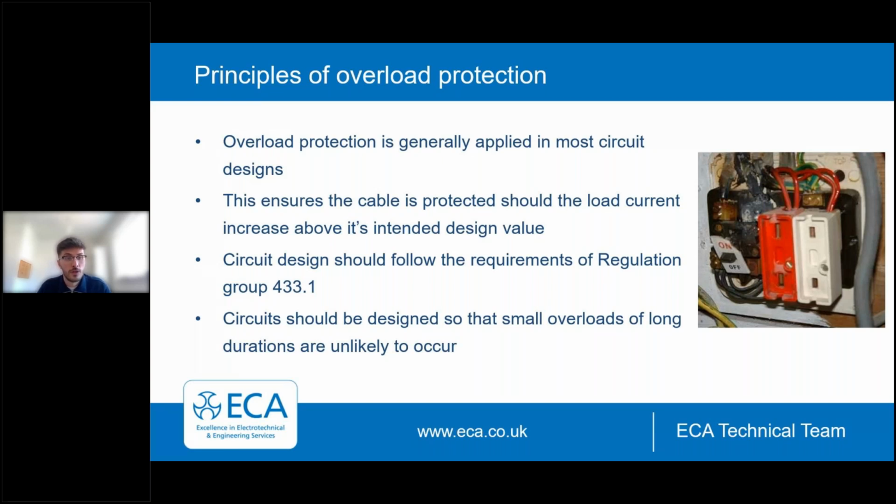And the reason we do this is to protect the cable should the load current increase above its intended design value. So we place our overload protective devices to stop thermal damage occurring to a cable within a circuit.